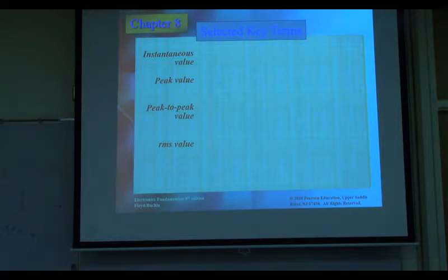If you apply an AC source to a load, for example a light bulb, with the peak equal to 10, you generate a power on the load. Now you change your mind, you want to change to a DC source, but you still have the same power. So that DC source voltage needs to be 7.07, smaller than 10, only 70%. So that is called the RMS value.